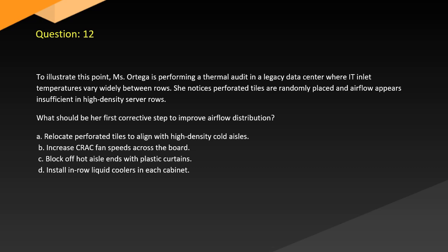A. Relocate perforated tiles to align with high-density cold aisles. B. Increase CRAC fan speeds across the board. C. Block off hot aisle ends with plastic curtains. D. Install in-row liquid coolers in each cabinet.